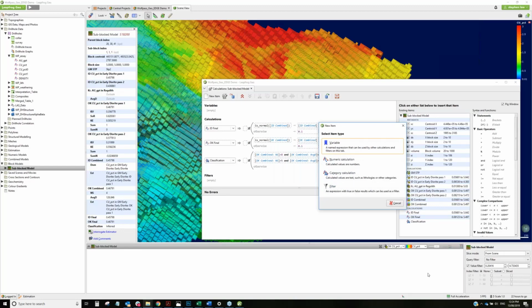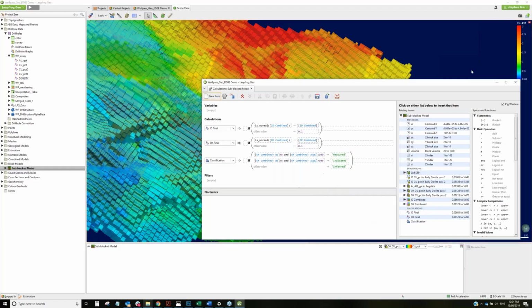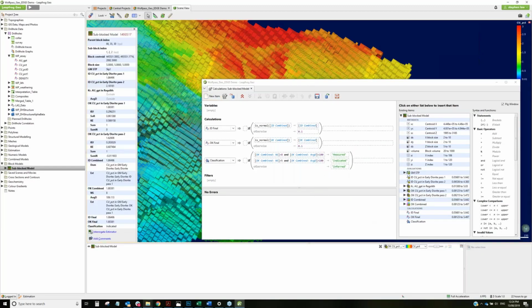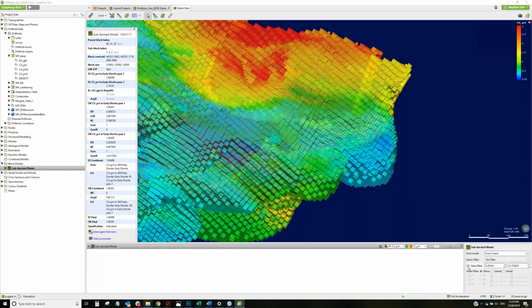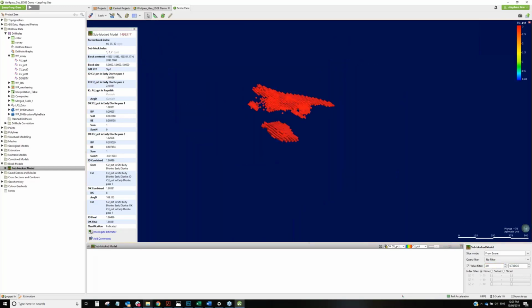So you can see here down in the right, when I'm viewing my block model, you've got some filtering happening down in here. So you can filter by just values. So if I want to see just where is everything, say above 3%, and apply that, it'll just filter those blocks out for me. But if I need something a little bit more advanced, like a combination of greater than 3% copper and greater than 5 grams gold, then I can build these filters over here.